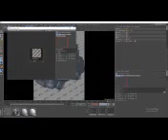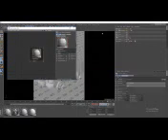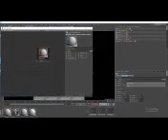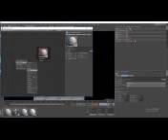In this lesson, we briefly learn about some of the more important Corona maps. The first important map is Corona Ambient Occlusion. Let's open up Node Material Editor, create a new Corona material, and assign it to this toy truck model. Add a new ambient occlusion map and connect it to the diffuse color input of the Corona material and run the interactive rendering.